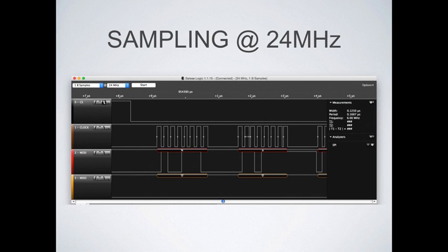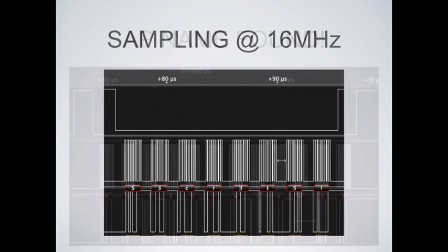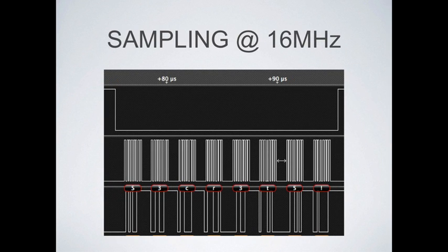But I opened it up in a text file, verified it was there, and now I'm back here looking to see it, and I was like, well, can I actually see the AP name? And there it is. You can see that this particular chip select went low, and a lot of data was transferred, which was this no secrets AP name, and then it went back high for this transfer.